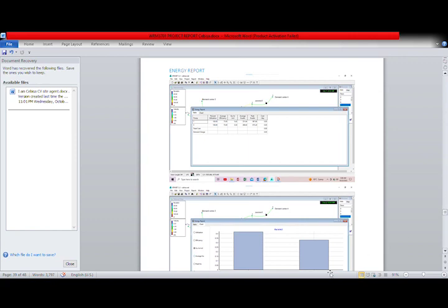All of these you get from your EPANET, where you go to report. Go into report for energies. You get in here, and it tells you the type of energy that will be used during this process.